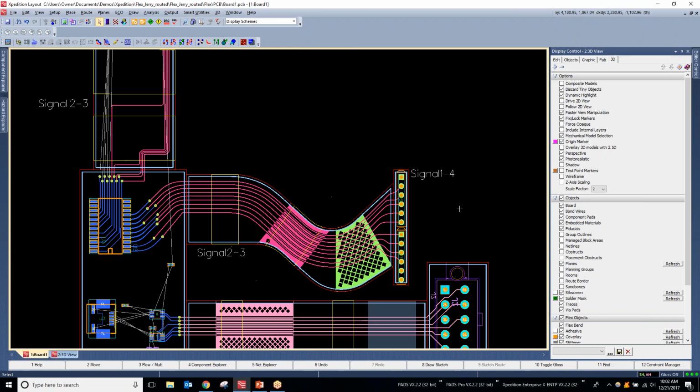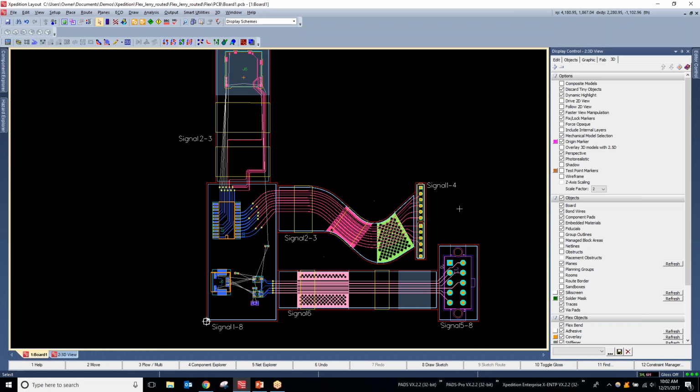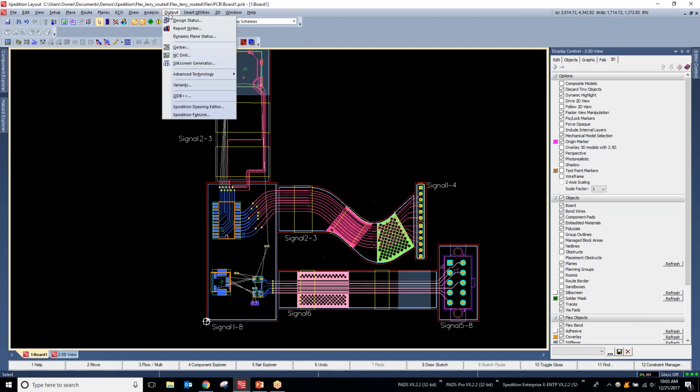So far, we have gone ahead and defined a master stackup, drawn our different board outlines for this design, associated all of those board outlines with the stackup that is necessary for it at that point, and then actually gone ahead and ran some DRC and visualized this in 3D. So I think these things in the Rigid Flex space can make it a lot simpler and easy to understand exactly what is happening in your design, and easy enough to go ahead and actually complete the design in Rigid Flex.